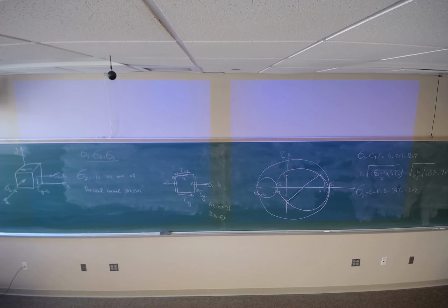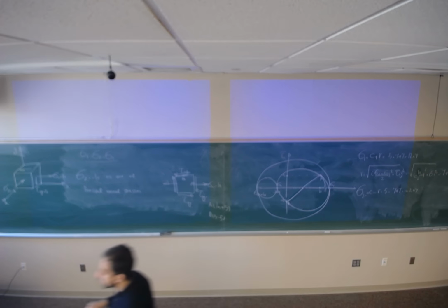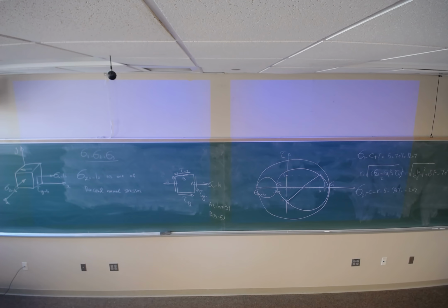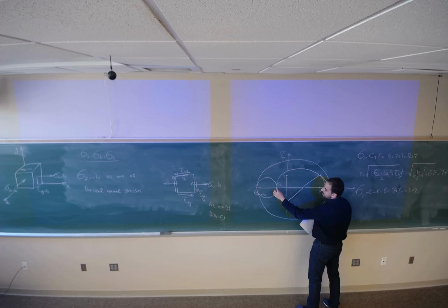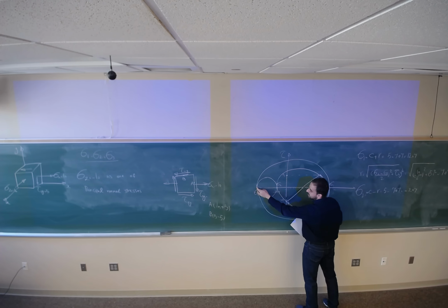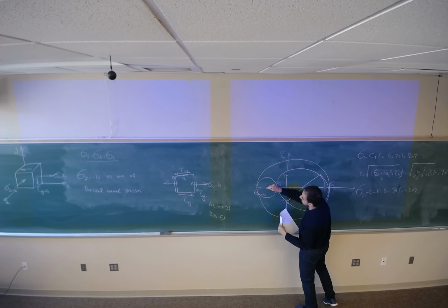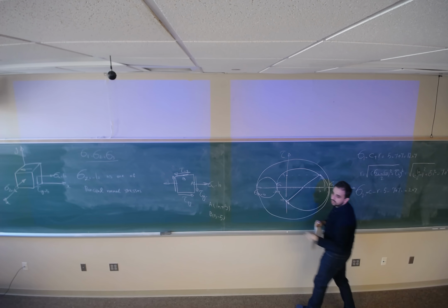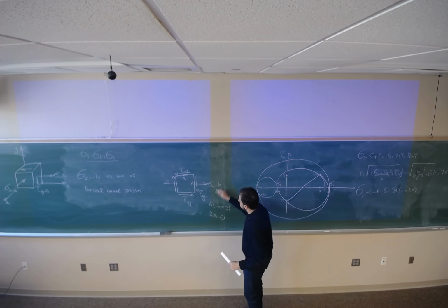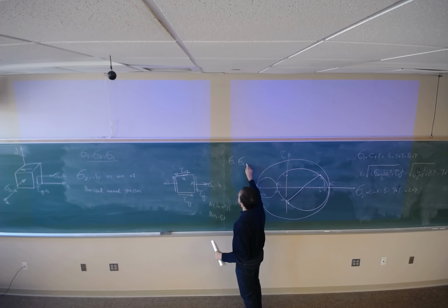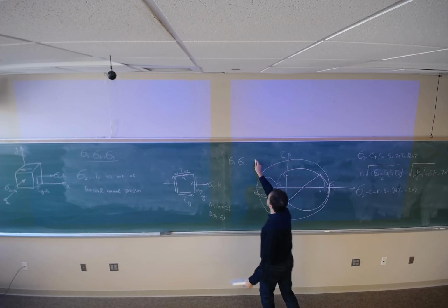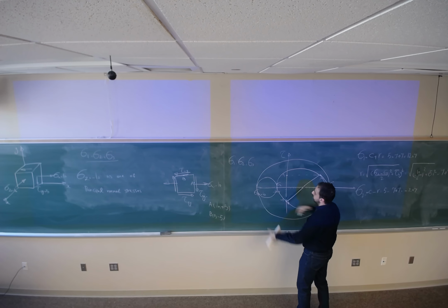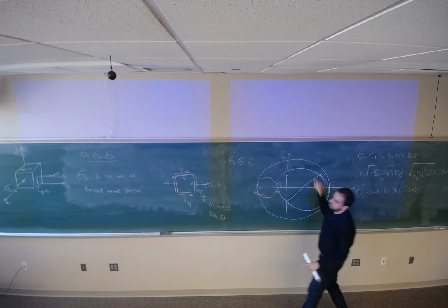How do you know where the smallest circle goes? We draw 3 more circles. If you know the principal normal stresses, you can connect them. The center is at the middle, and you draw a circle with that radius. So what I did, I could find sigma 1, sigma 2, and this one is gonna be sigma 3 because it's the smallest one. So then I just had 3 circles passing through these 3 points.